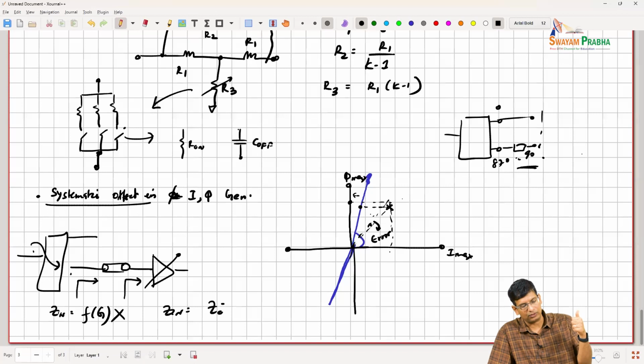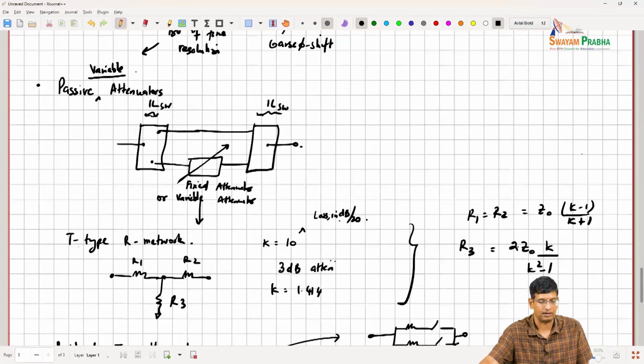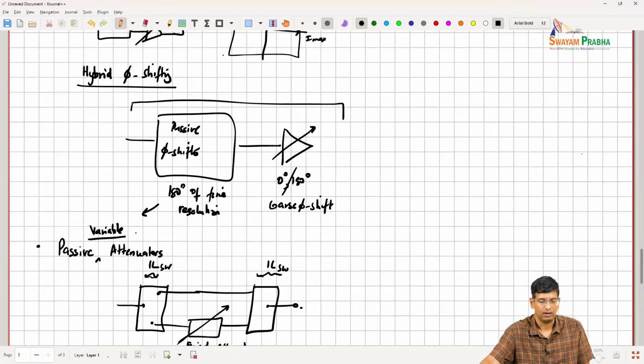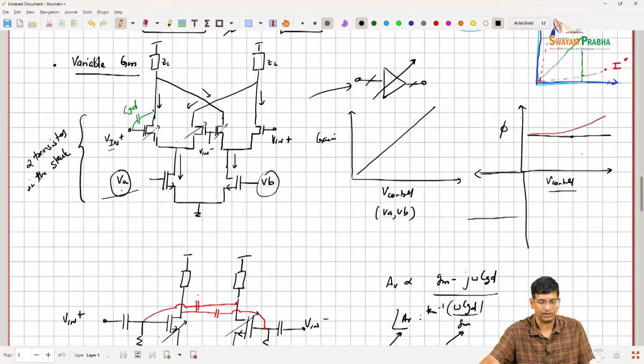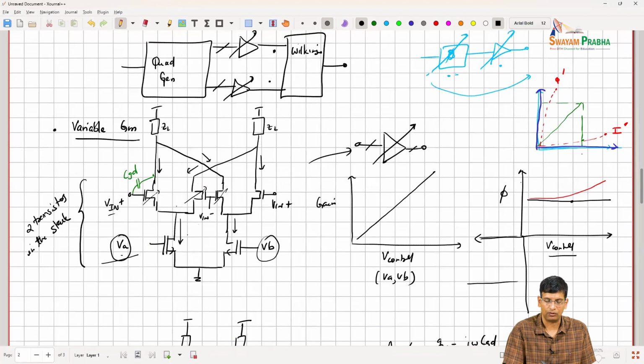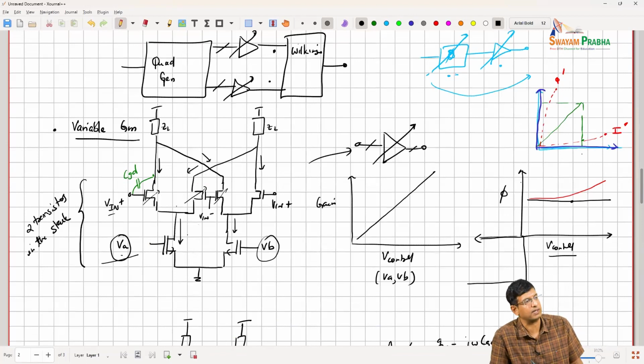But then you'll find that those weights start changing across frequency and they vary in a nonlinear manner. So that means in practice, the control voltages that you have to generate, right? For example, you might find that I generate this control voltage with 5-bit precision, but I get only 4 bits of phase shifter precision.